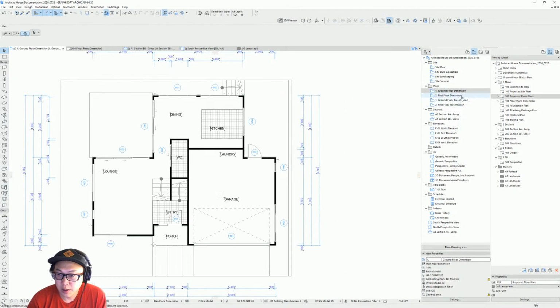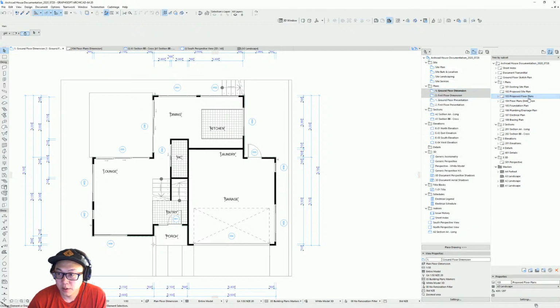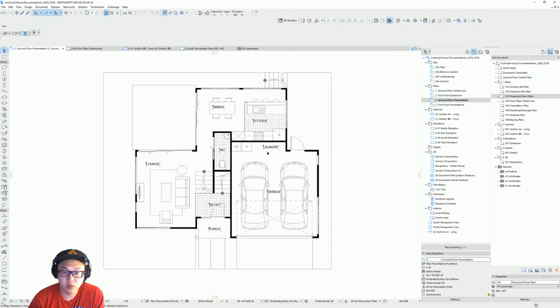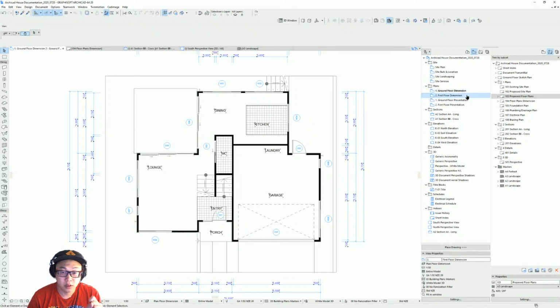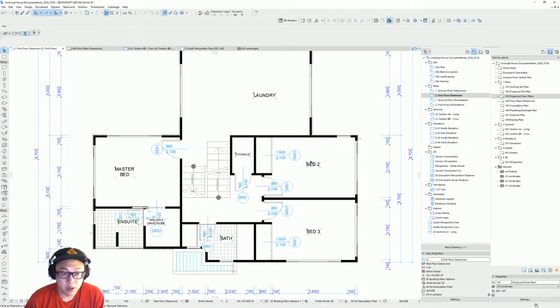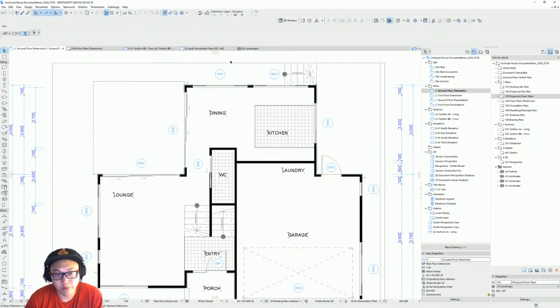Okay. Make sure you change that to markers so that it will appear, because if I go to presentation, they're not showing. And yep, I have to do the same thing upstairs. So I'm just gonna check the ground floor first. We had how many doors? Up to 6, so the following one will start at 7.